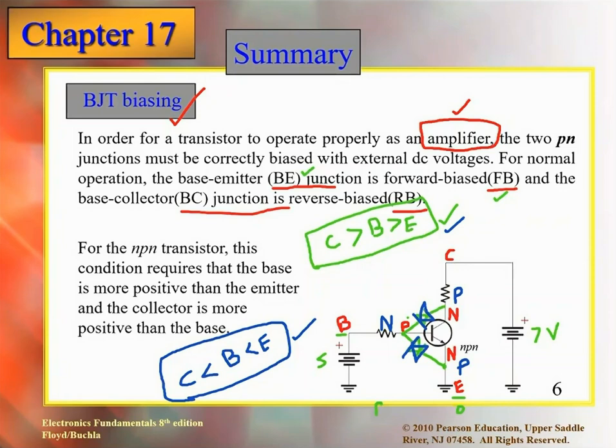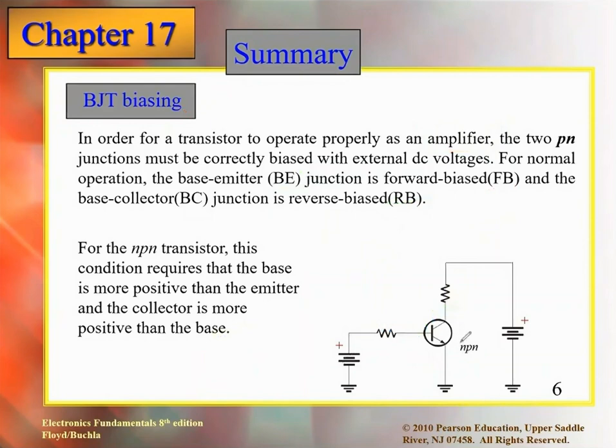All right. So you understand how we set up this transistor in an active region by making base and emitter forward biased, and base collector reverse biased, by putting in these extra batteries. Now girls, how many batteries am I applying here to make these two junctions forward and reverse? Two batteries. Now I'll show you another way to make them forward or reverse with the help of only a single battery and a voltage divider circuit. We'll see this one later on. For now I just explain the concept to you.